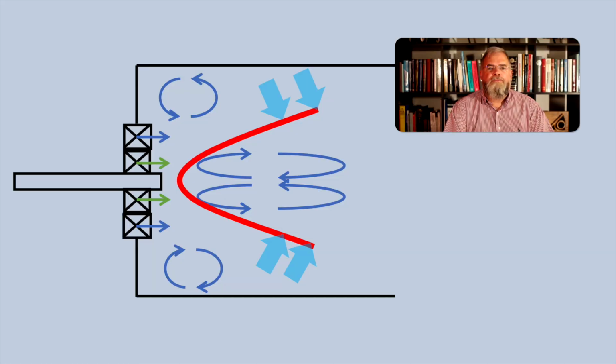The colder air from this outer swirler, though, will still mix with this flame further downstream, cooling the flame there, slowing reactions, and reducing the rate of CO oxidation. So these burners will also suffer from higher CO emissions at part load. Another disadvantage of this system is that because each burner is surrounded by cold air at part load, when the outer fuel stage is switched off, it is not possible for nearby burners to help stabilize or reignite the flame of any burner which encounters flame stability problems.